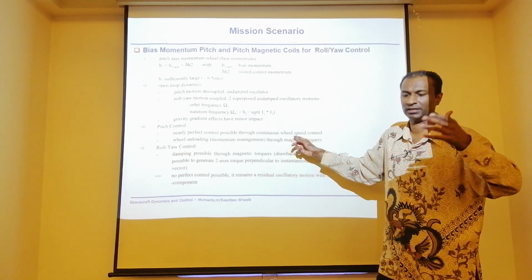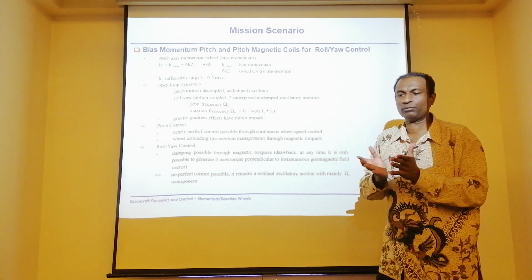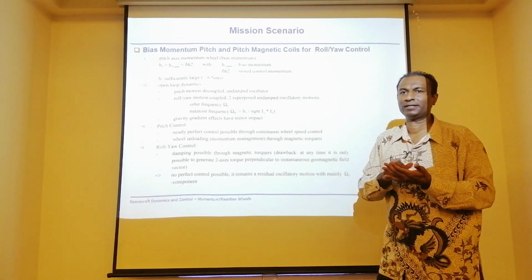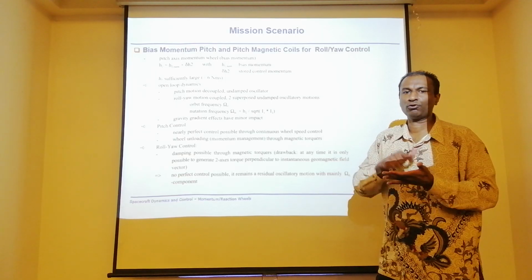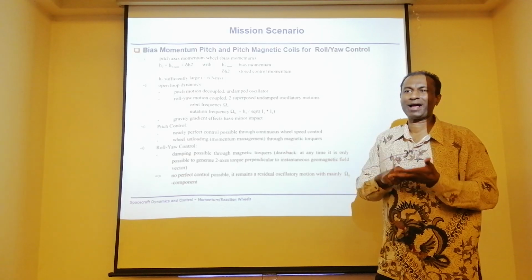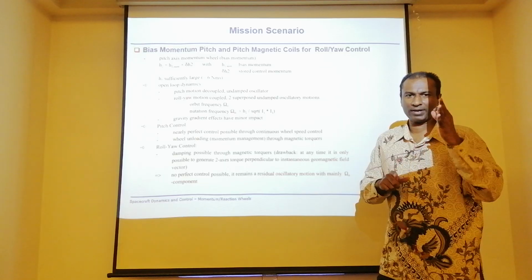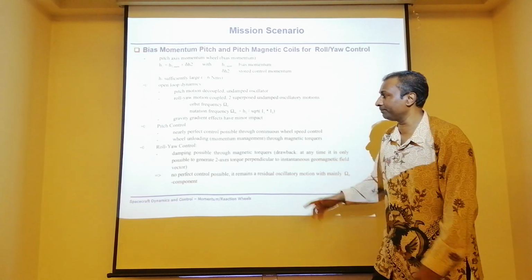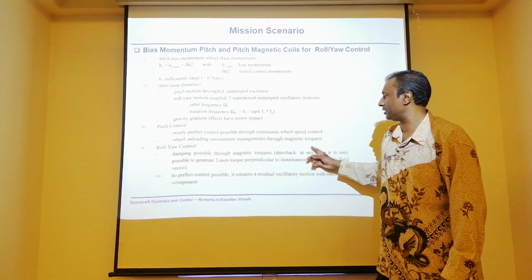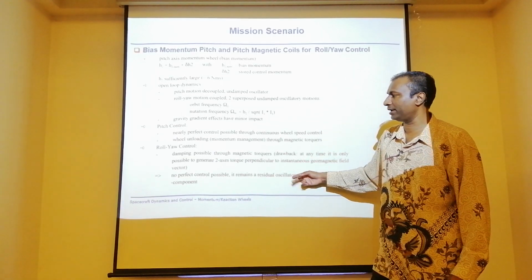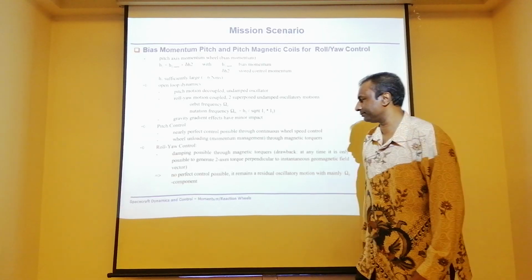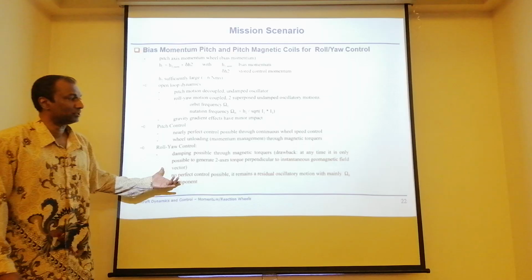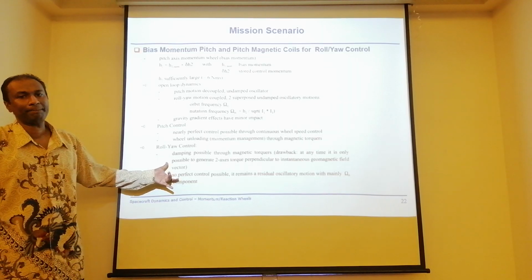If you want to buy a reaction wheel, the manufacturer will specify this is going to give me an accuracy of, let's say, 0.001 degree. So that's the accuracy that you have in the pitch. Okay. Wheel unloading, basically we can do for roll and yaw. Our magnetic torques, we have also proven, can dampen that.